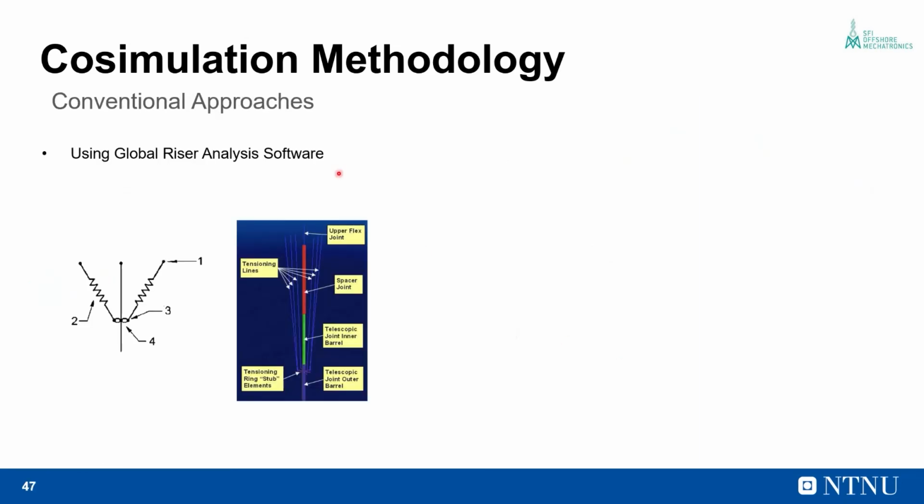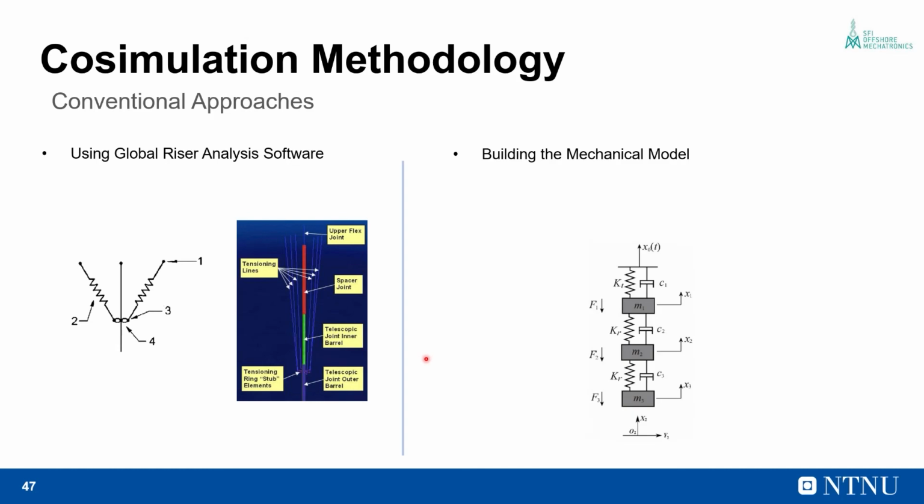And in the conventional approaches to drilling riser analysis, the tensioner cylinders are usually modeled using spring damper elements in software like Orcaflex and Flexcom. We also have another methodology where the entire system is modeled as a spring mass damper system, with the riser tensioner tension and the damping due to the recoil valve being modeled in the spring mass model.